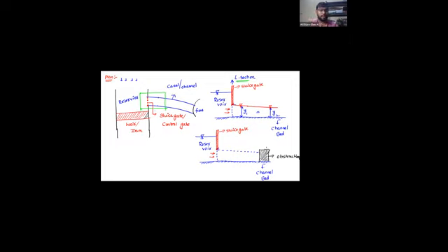Repeating the point again, when there is an obstruction, if the flow gets obstructed, the kinetic energy will decrease and it will convert into potential energy. What is meant by potential energy, my dear? The depth of flow or not? Potential energy means the depth of flow. So once the flow hits, the water level is not going to be the same. The water level is going to rise.